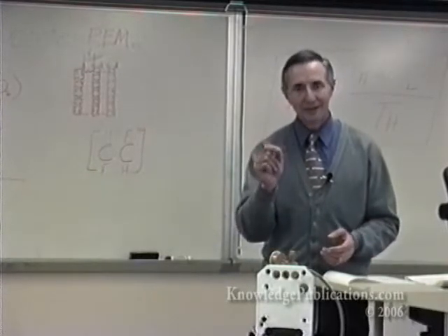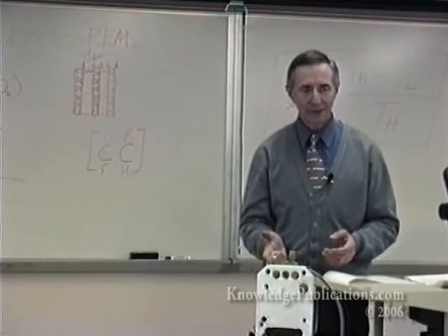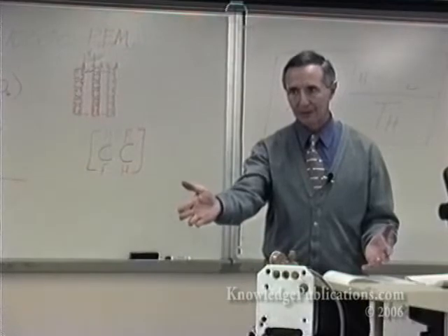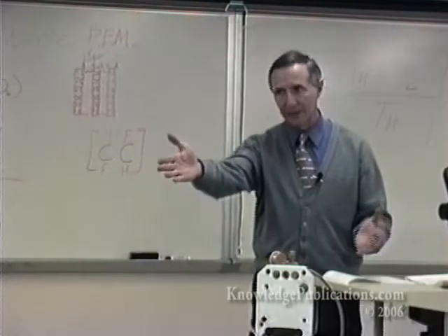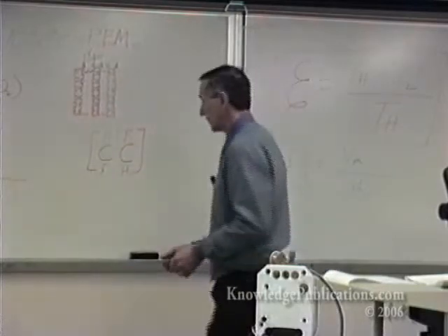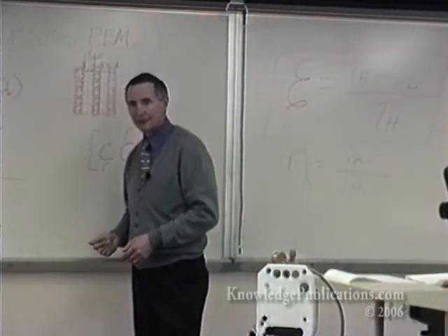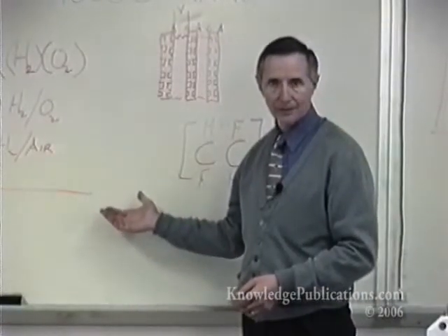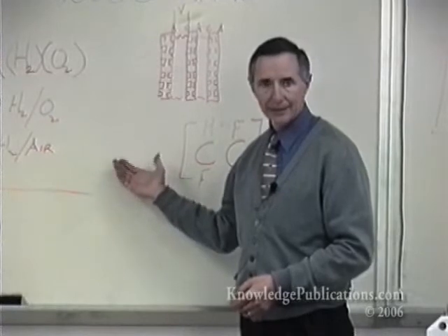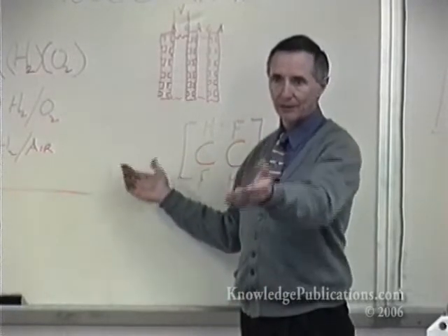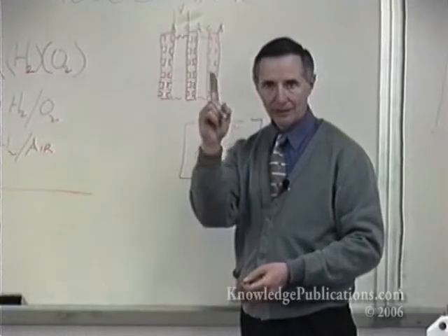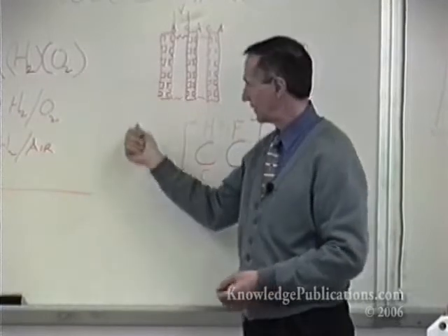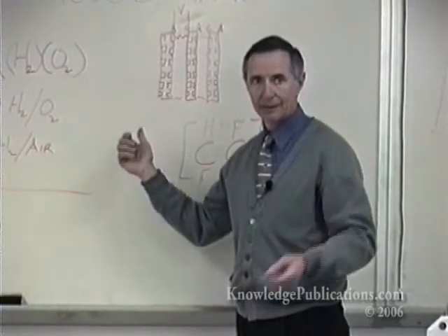On the oxygen issue, this is also a better answer, because however you're analyzing the oxygen consumed, this is less than the gas turbine would have consumed, or internal combustion, whatever that other approach would have been. This one can be less. In terms of other resources of the earth, and the phosphoric acid as an example, the phosphoric acid doesn't disappear. You're not going to have carloads of phosphoric acid coming to the plant. This is a one-time inventory of platinum, phosphoric acid, carbon plates, or whatever plate the system runs on.